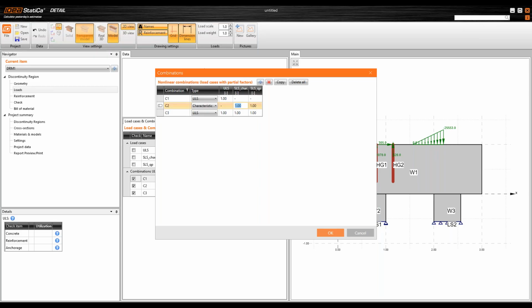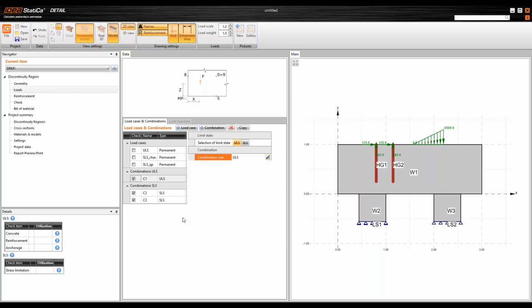So it means that here will be 0 for the ultimate limit state and serviceability limit state, quasi-permanent. And the last one will be quasi-permanent. So you have to create this diagonal matrix like here, because our design values confirm that it's automatically split. And that's it from the point of view of the loads, and you can move on to reinforcement design.